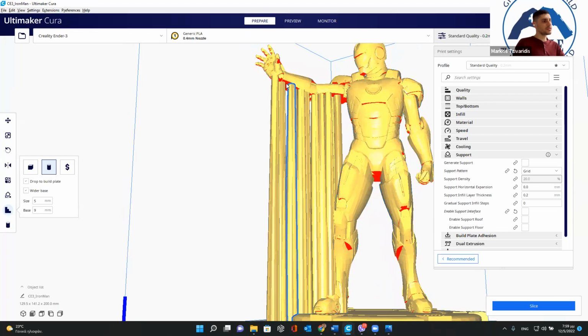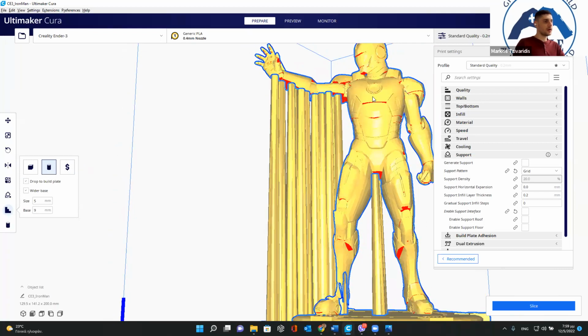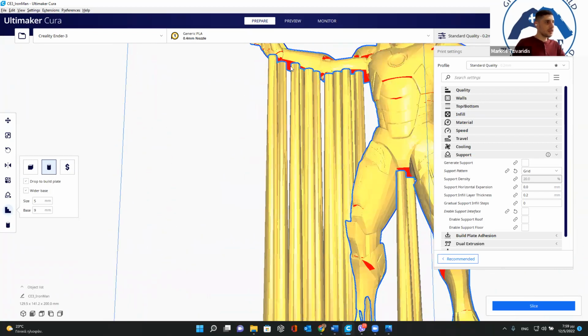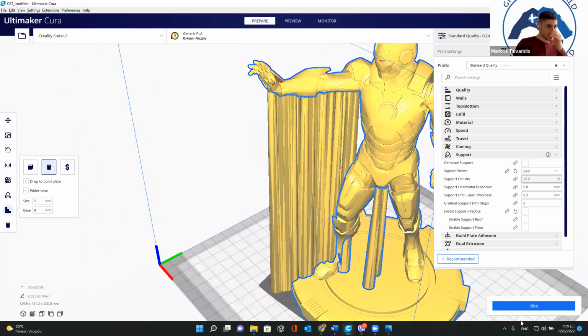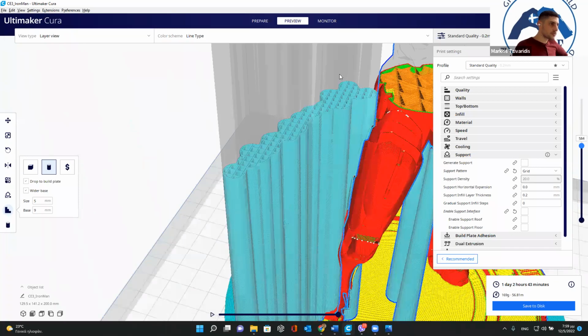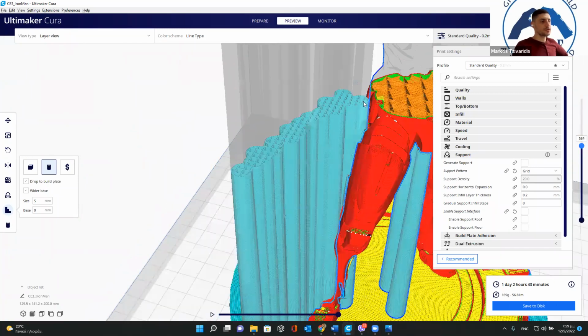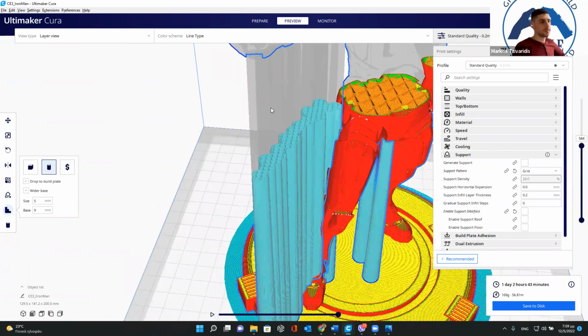The great thing with this, and of course, here on the bottom, is that if I actually click everywhere, what will happen is that when I slice it, it's not going to be like 10 different supports. It will look like actual supports, like one support pattern. So that's a great thing. So you don't use a lot of material.